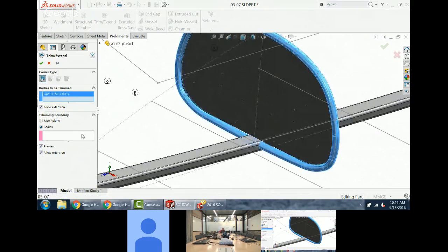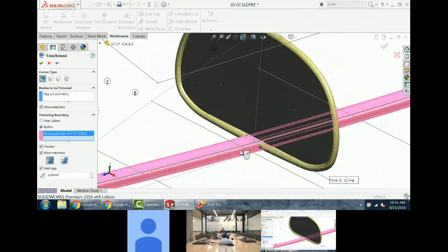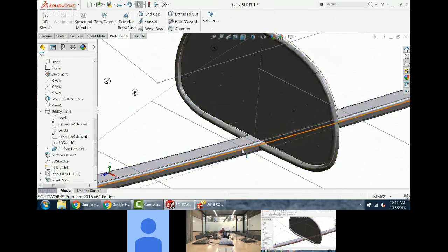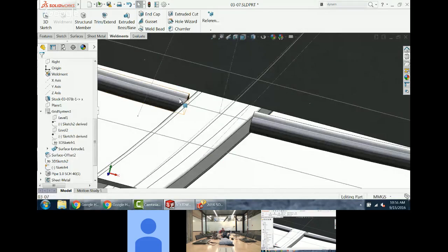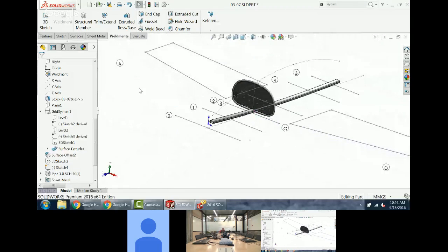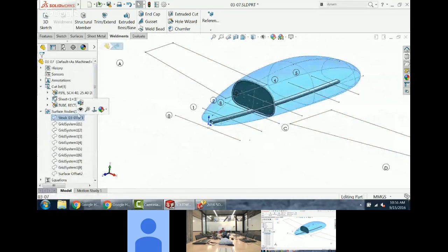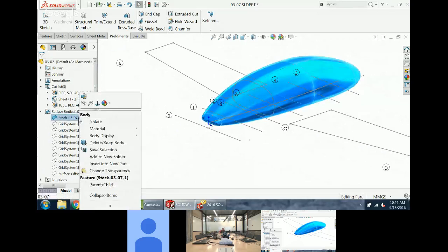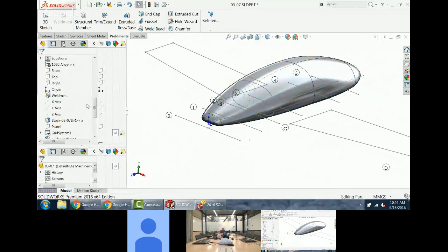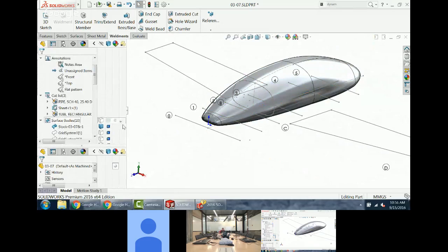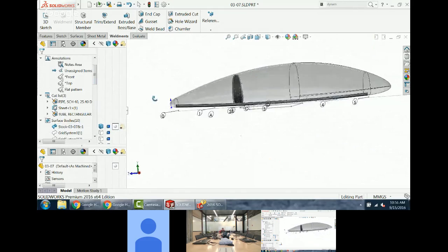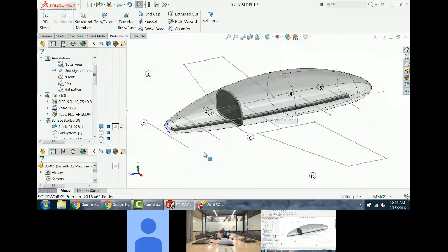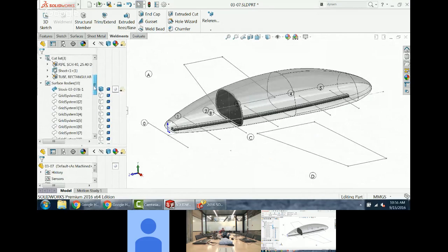I want to trim this thing. Using that part, that'll snap that piece and weld it to there. And this all is going to fit magically inside of that original shape. Make it transparent so you can see. I can start building this piece by piece using these stations for the wings and for the frames of my hydroplane.